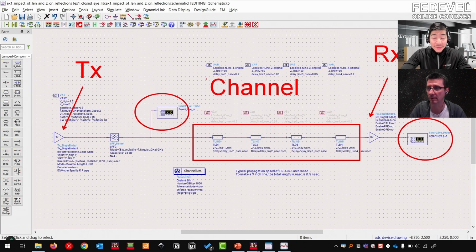And if you notice in the middle here, Robert, since we're talking about reflections, I have created variables for the impedance and delay of these 4 different line segments. Once we simulate, the first case, number 1, as we've seen here, and we have case number 2 at the bottom here. Case number 1 is all 50 ohm lines, which means it's a very controlled impedance line environment. We should see the eye as open as it can be. That's what we expect. Highest quality signal.